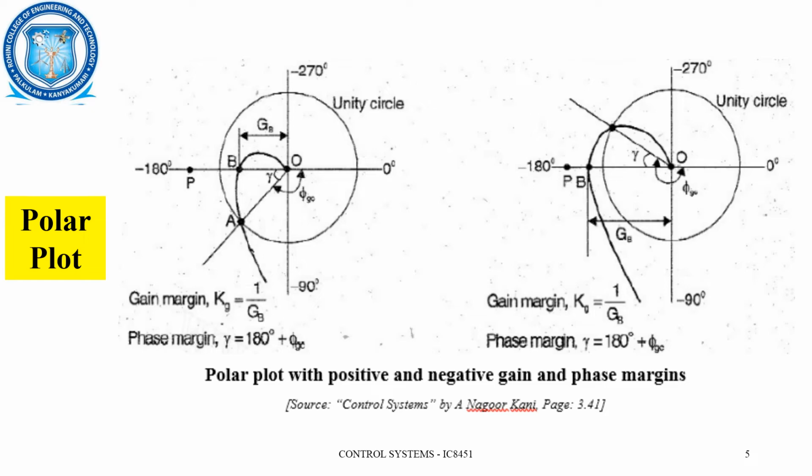So what we used to do is consider these circles for representing the magnitude of the loop transfer function and these straight lines as the particular angle. For example, this is a 0 degree line and next this is a 90 degree line. So between them a 45 degree line will be there. Here it will be 10, 20, 30, 40, 50, 60, 70, 80 degrees. Similarly, we'll have straight lines. So the straight lines will be representing the angles and the circles will represent the magnitude, of course.